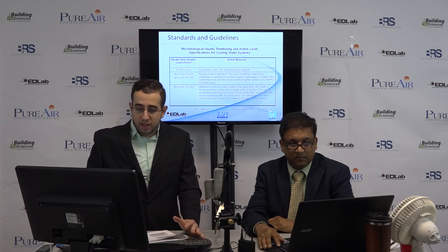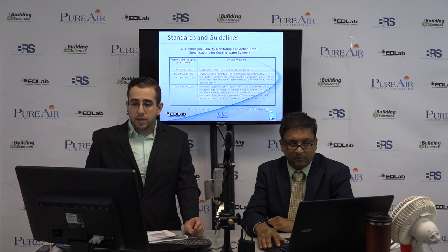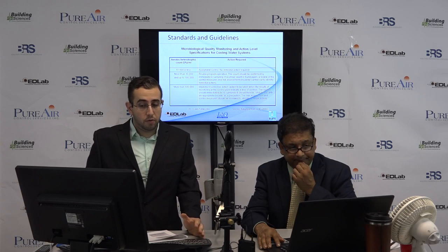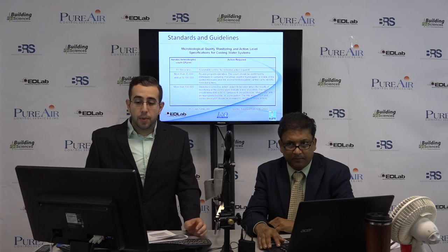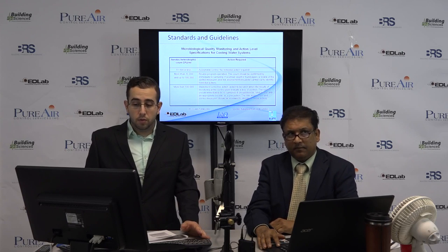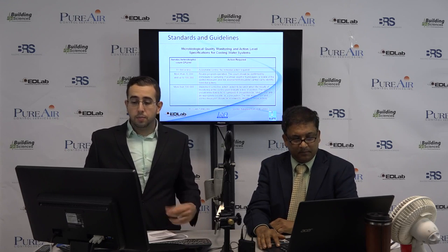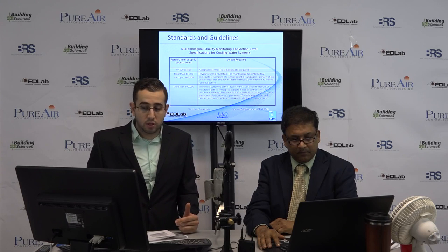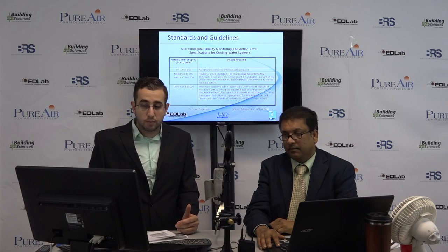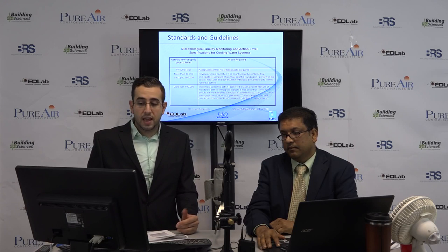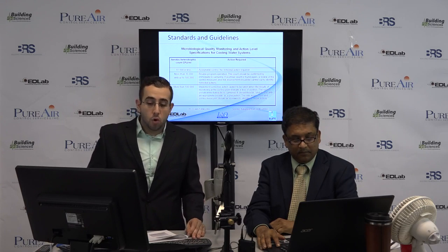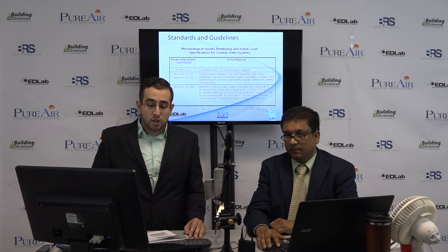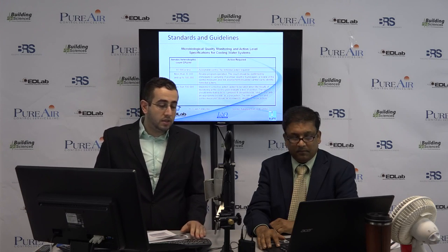This one is the HSE guidelines. These are for cooling water systems. If you have 10,000 or fewer colony forming units, that's considered acceptable. More than 10,000, but up to 100,000, we have to review program operation. This needs to have resampling performed just to make sure that Legionella was detected properly. If that is the case, then control measures and a risk assessment need to be performed. And if there's more than 100,000, then corrective action needs to be implemented and further steps need to be taken.